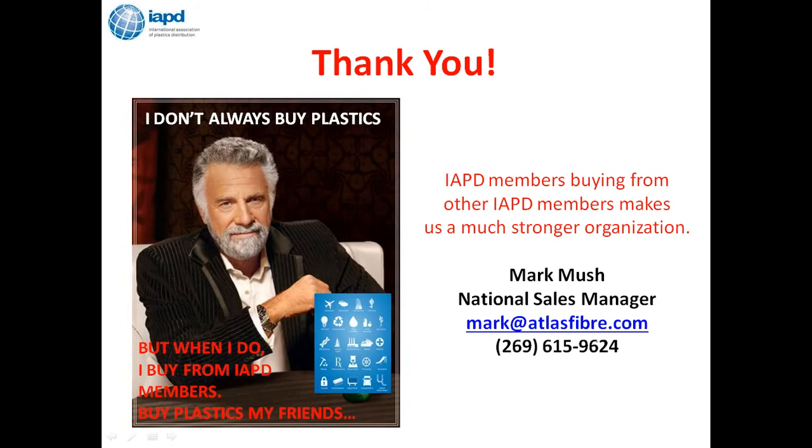Okay. Is there centerline porosity with the rods? In rolled and molded rods, I would say yes, there is some porosity. You can't get as much pressure on these in the press, and as that material squeezes down towards the center, you definitely get a collection that is heavier in resin than in the main material, the cloth that's in there. Also, in molded rods, as you get up over 1 inch, you can see some radial cracks in the interior because as it comes out of the press, the inside of the rod is cooling at a different rate than the outside. And that difference in cooling rate can create some stress fractures in there.